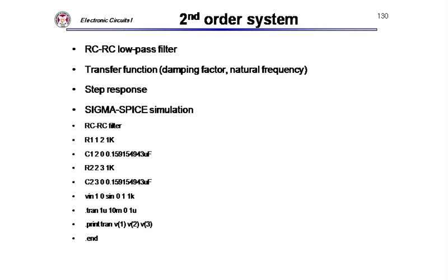You should be familiar with SPICE, because of the lab. So this is some RC filter transient analysis. The .tran line has something like 1 microsecond, 10 millisecond, 0, 1 microsecond.